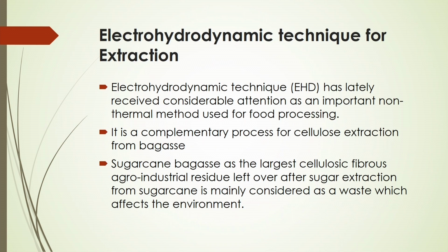Now, based on that thinking, you will see that several techniques are coming to intensify the extraction process. In that case, electrohydrodynamic technique is one of the important extraction techniques for its intensification. This electrohydrodynamic technique has lately received considerable attention as an important non-thermal method used for food processing. In that case, you can save some energy, whereas in conventional techniques thermal energy is used for extraction of valuable products from solid materials. So, if you use the electrohydrodynamic process, you can save some thermal energy.